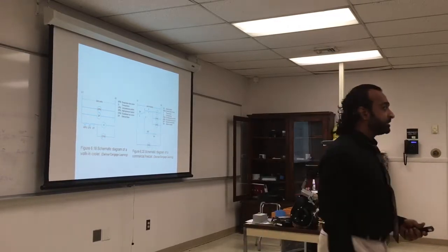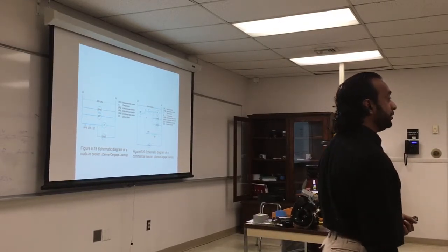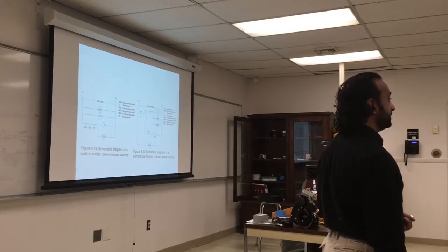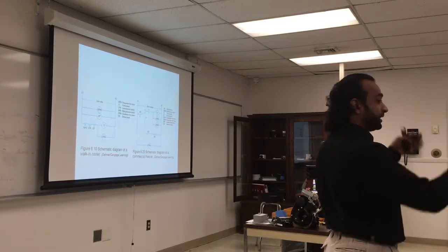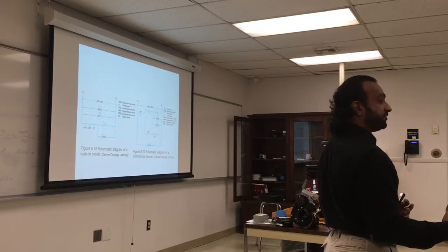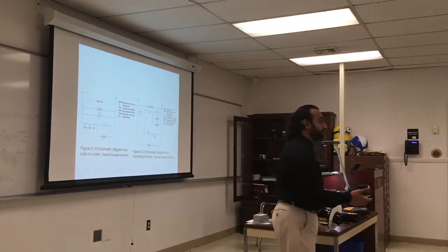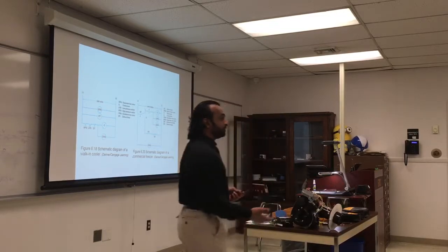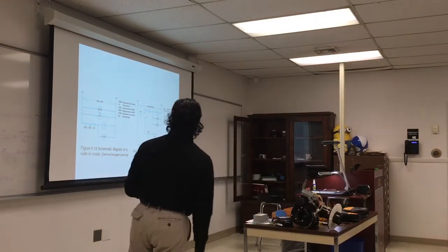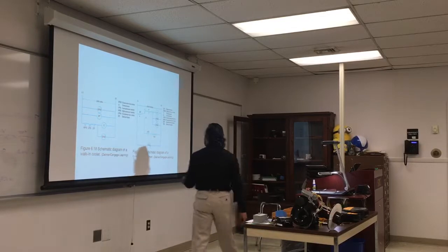Most ACs in the 80s usually have that. You wake up early morning and the AC stops working. It's humming, but there's no air coming out of it. And you look at the evaporator, and there's a lot of ice in it. So now they stop that problem by reducing the amount of humidity, and also by having a sensor that will turn off before it accumulates a lot of frost.